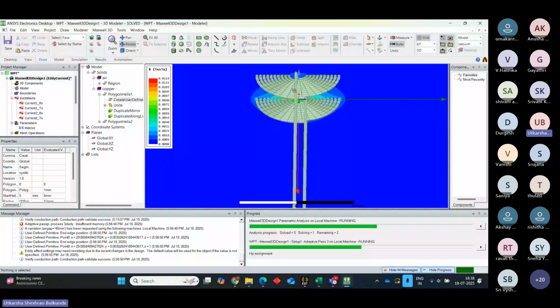We have just taken out these wires from our spiral coil structure and given our excitation through them. But one thing is important: this wire should be long enough that it touches your region, but it should not go outside of your region, or be less than your region. It should just touch your region, right?